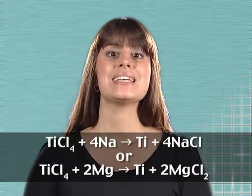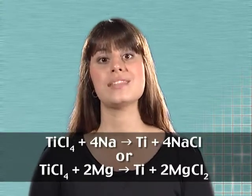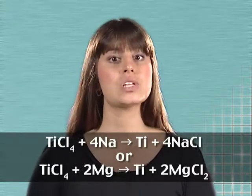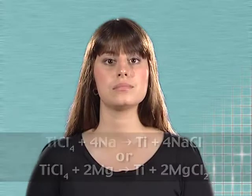Finally, titanium is separated from the sodium chloride by the addition of water. Sodium chloride dissolves and can be washed out, leaving granules of titanium. There are high costs involved in this process, and so titanium is an expensive metal. How is it possible to get the titanium so pure? Now, in the first stage of the process, titanium(IV) chloride liquid is formed. Liquids can be purified by fractional distillation. The pure titanium(IV) chloride eventually yields pure titanium.